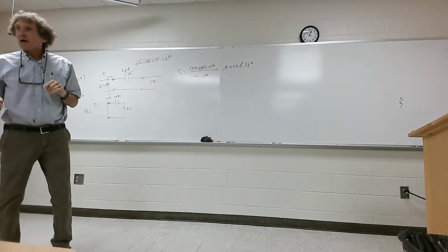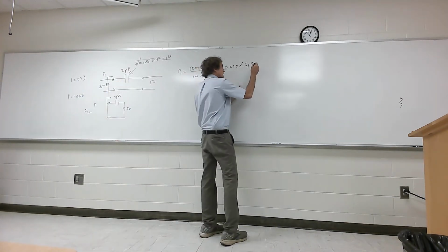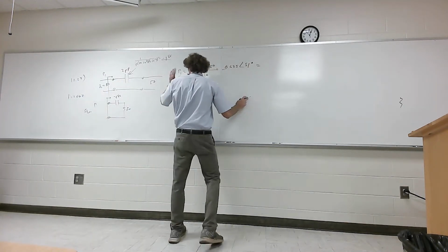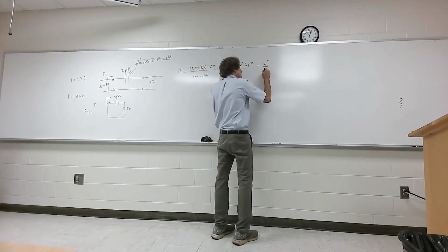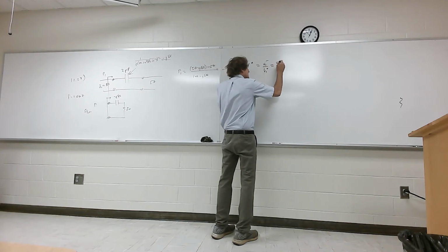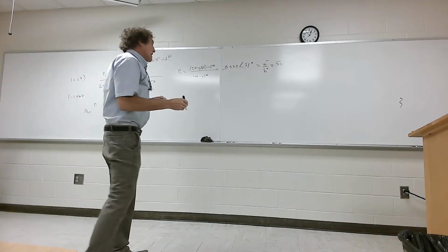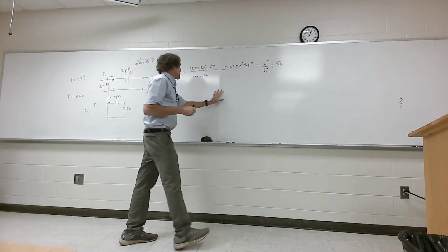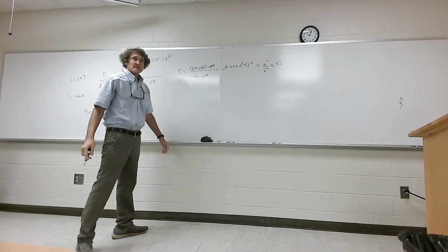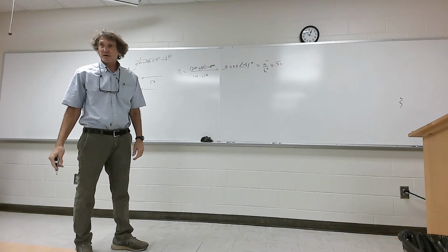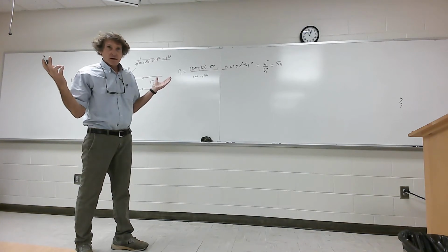Now, that is S11, isn't it? By definition, this is a matched load, so there could be no reflected signal coming in there, so that is V1 minus over V1 plus, and that's S11. You all agree? I think we got minus 51. Minus. Thank you. All right. Really, the 50s cancel, so it's minus 80j. It should be a minus sign, just looking at that. Okay, now we've got that, and the minus sign is important.